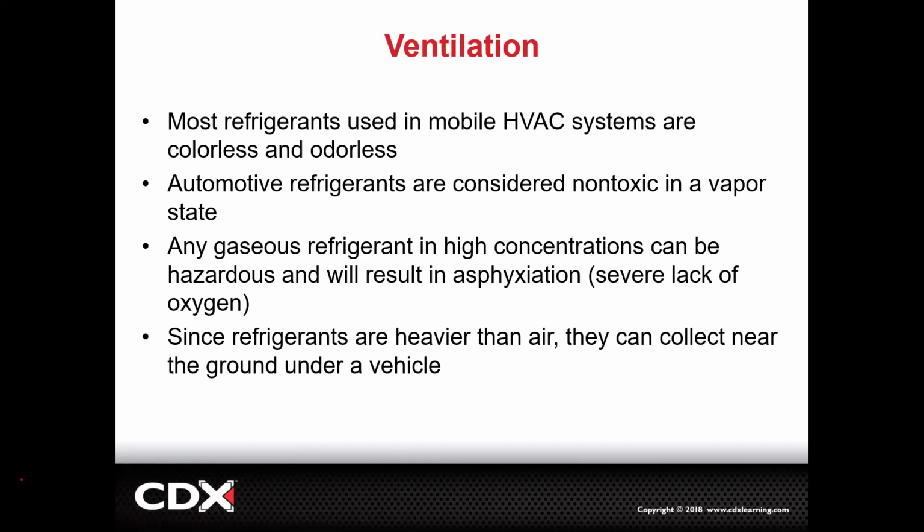Exactly. You're going to be breathing, but you're not breathing oxygen. You're going to be breathing refrigerant, and refrigerant will displace the oxygen. So it's not exactly like drowning, but you're not getting air, you're not getting oxygen. There is no oxygen because you're surrounded in a low-lying cloud of the refrigerant. So again, that's why we're worried about ventilation. Okay, so if you feel like you're not breathing, get out of there.